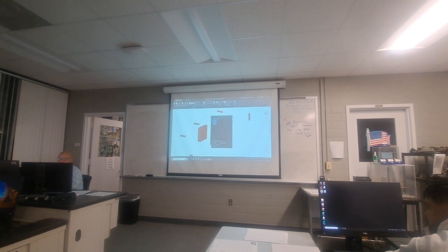So any questions about those 3 blocking methods, actually really 4 if you count the XREF? We had the XREF, we had the copy to clipboard, and then Control V or Control Shift V to paste it into a drawing. And then we had just our regular create block, and we also had our write block. So any questions on those?